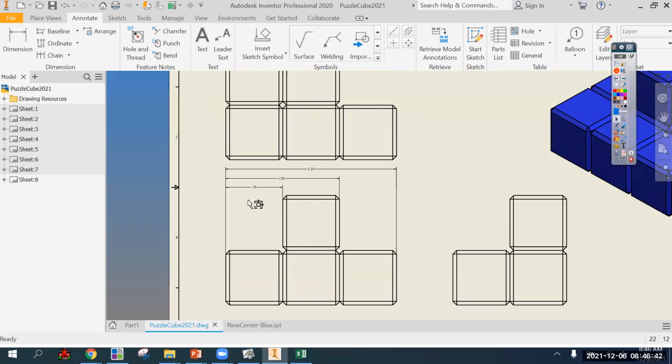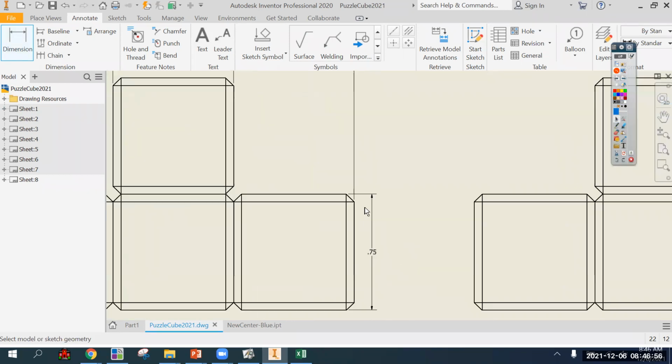So in the width dimension, we dimensioned every time something happened, and there are 3 width dimensions. Now height, from the base up, the first thing that happens is the height dimension. Now, this wasn't a conflict the first time we did this because of the way the lines work, because we want the dimension to this height here from all the way at the bottom, we're going to click somewhere on this edge, but then our extension line crosses over, which makes it a no-no, which means we need to put the first height dimension here instead of on the front view.